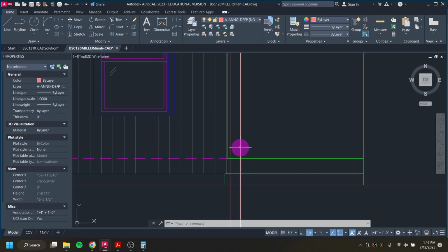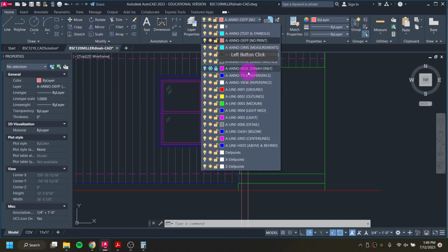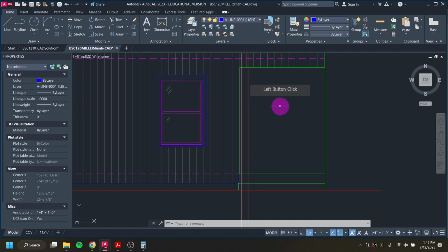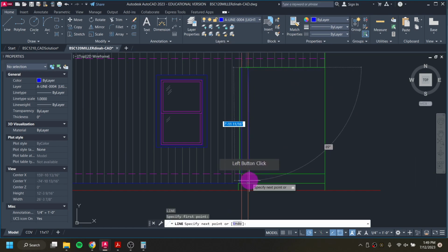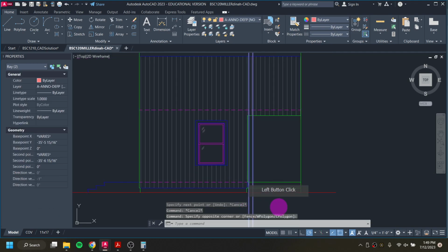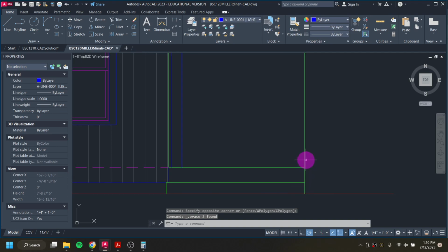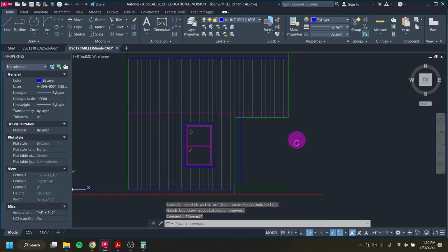So that's going to show me where this piece is for my pole that's holding that up. Line, and I'll just draw a line on top of this rather than trimming it. The reason I'm doing that is because when I hit escape, it'll be easier just to delete this. And then there's also another 2x8, or excuse me, 6x6, sitting right here on this edge of it. So I'm just going to shorten that line down.